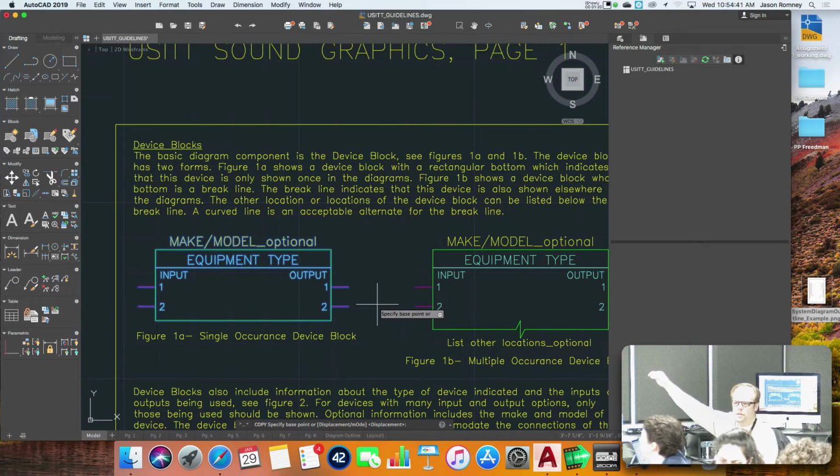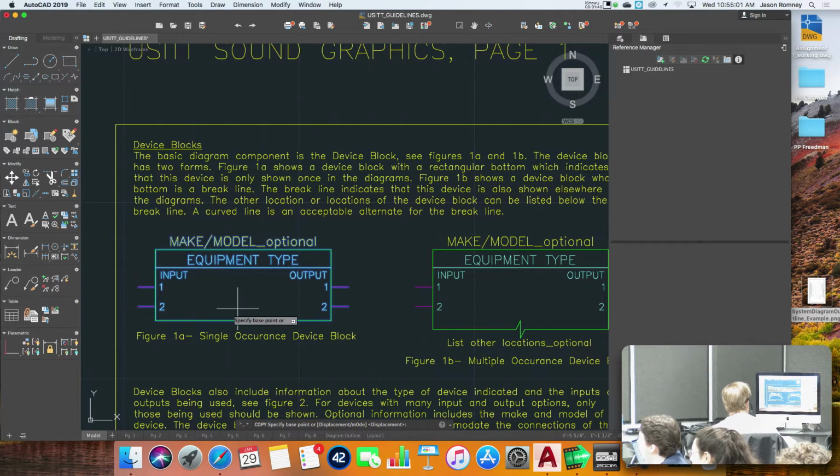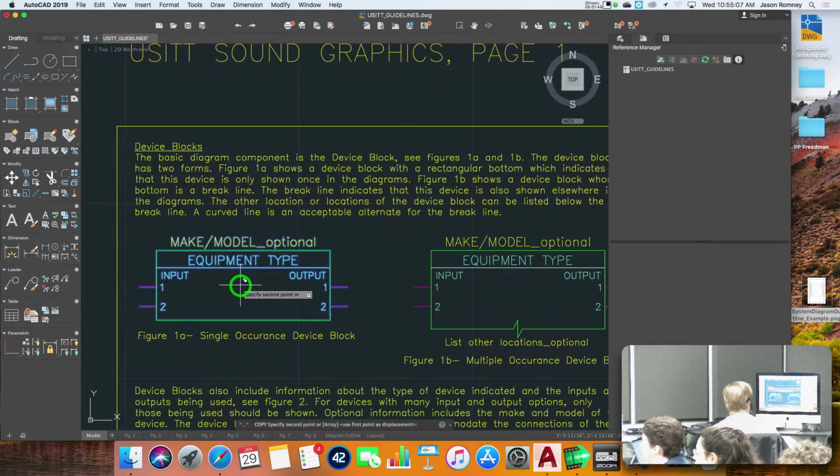Okay? So you can't, I mean you can, but it's hard. But usually you don't copy things by putting in absolute coordinates. You usually copy things by putting in relative coordinates. Right? Make a copy of this thing and place the copy of it in this location relative to the original. Okay? So you just have to pick a relative start point. I'm going to take, it doesn't really matter, but I'm just going to click somewhere inside of this thing. So start somewhere where this thing starts, so just click.